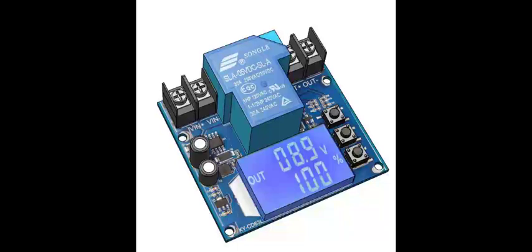Welcome back. Today we're going to take a look at setting up a mesh for conjugate heat transfer, CHT. Going to use an electronics component board with some components and look at the steps required to get a conformal or watertight mesh. One of the issues with conjugate heat transfer is quite often the geometry is just packaged loosely. It's not exactly aligned. Components are interpenetrating and they're just basically in the right place.